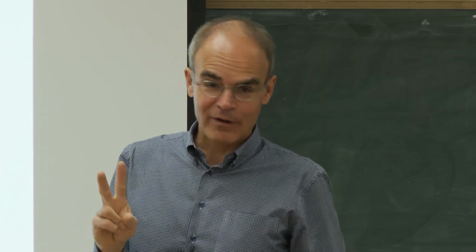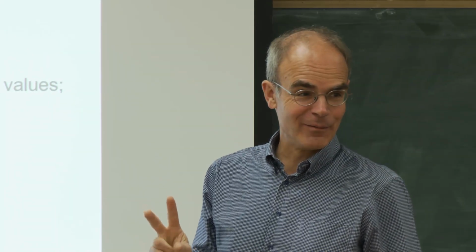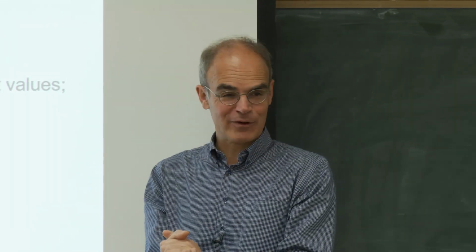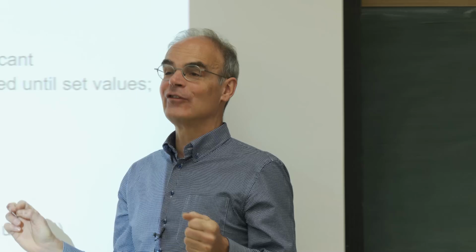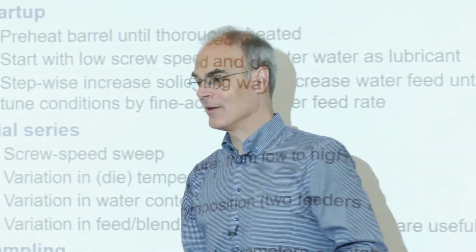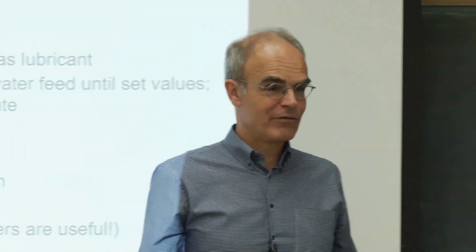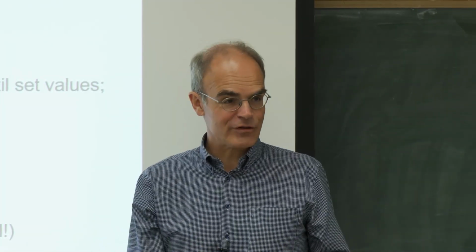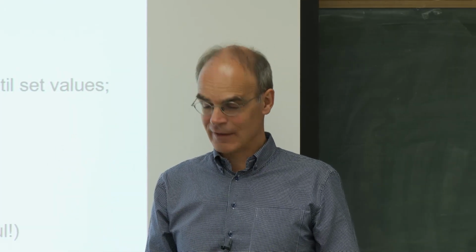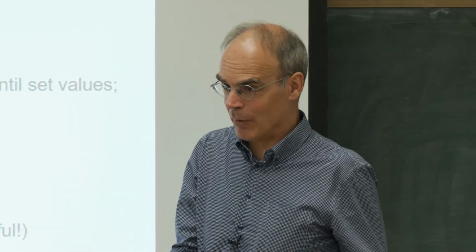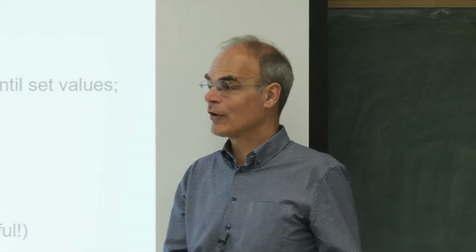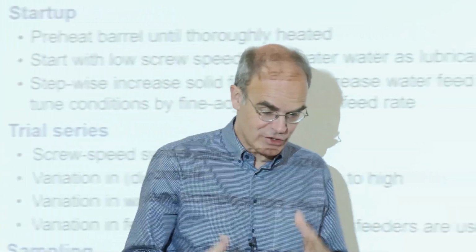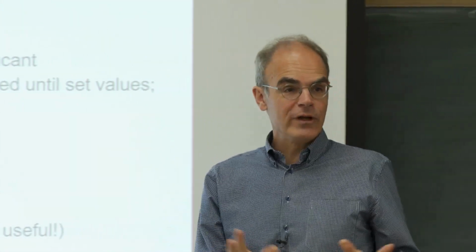There's also a reason why I wanted to have two feeders with our extruder. You can load one feeder with one blend composition and already have the second one ready with the other one. It's seconds and you switch over. Switch the feeder in, and within 5-10 minutes you're running with your fully new blend. Then, if you have enough staffing around, someone can clean that first feeder and maybe load it with the third blend. So that's why two feeders are convenient, especially if you want to run a lot of compositional variations, a lot of variations in how you mix things together.